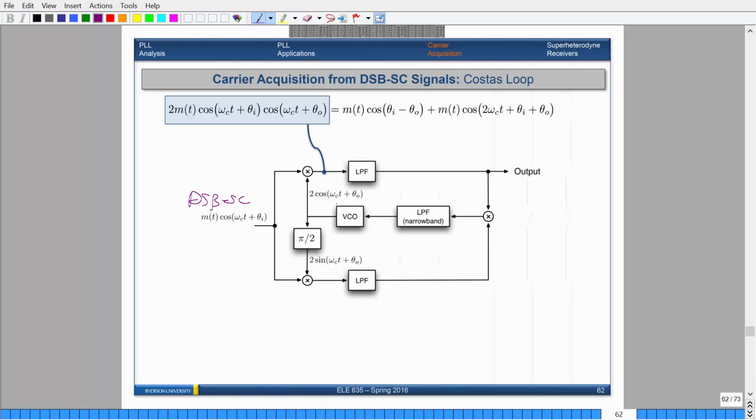This is just a standard voltage controlled oscillator that is generating some cosine wave. So we have a voltage controlled oscillator that generates a carrier frequency, and you have to make sure that they match, or are roughly the same. Okay, and then we have a phase shifter that will generate a sinusoidal equivalent.